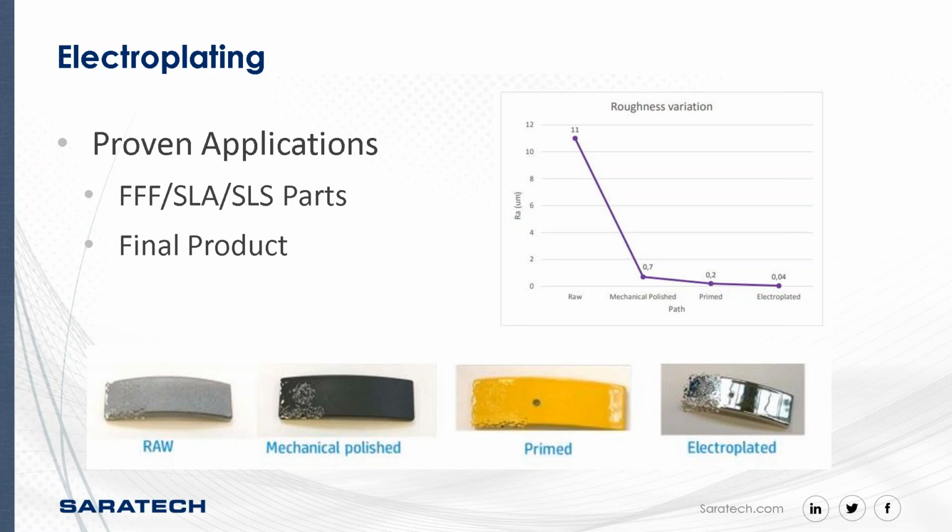Electroplating is a process that adds a thin layer of metal to a metallic object. At a basic level, it consists of dissolving one metal in a solution and subsequently attaching it to another metallic surface using an electric current. The target surface must be able to conduct electricity. So raw parts can be electroplated, and that'll give them the desired physical properties.